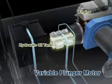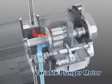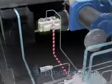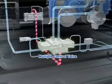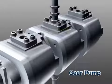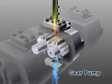First, the variable pump is driven by an engine, sucking hydraulic oil from the tank. The oil is then sent to the multiple control valve. At the same time, the gear pump sucks and delivers hydraulic oil to the remote control valve.